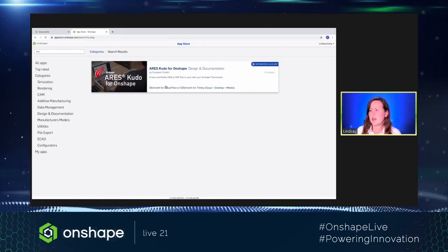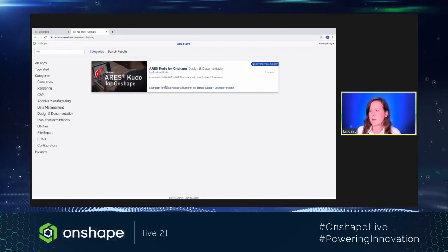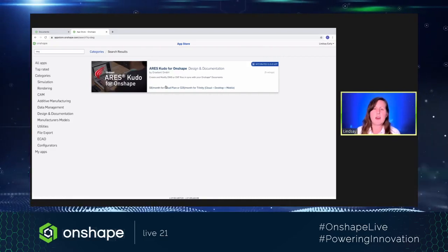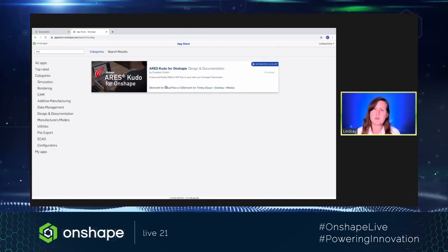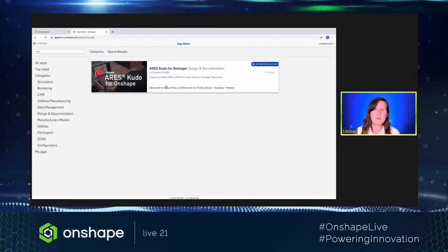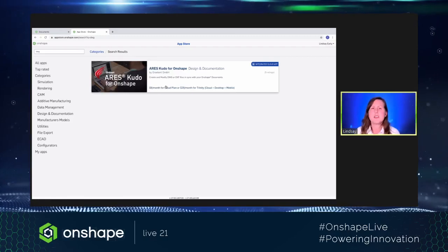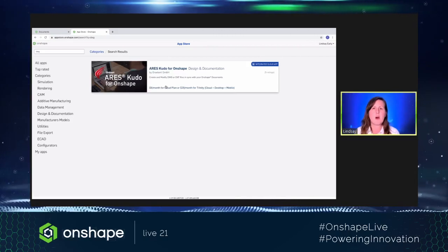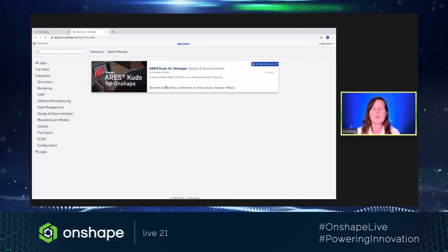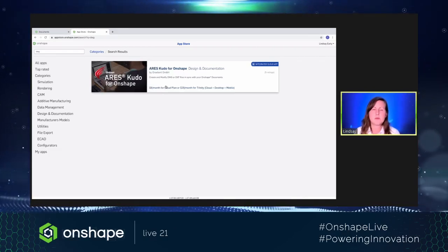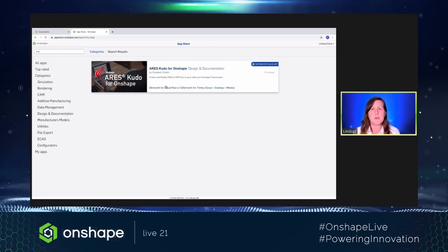So someone asked, do you have any best practices to get assemblies into working shape once we start our migration? So if there shouldn't be any movement in the assembly, the easiest way to get going is just go ahead and highlight the whole thing and use a group mate. The way that works is it basically locks all the parts with respect to each other. So when you put it in a higher level assembly, they're not going to move all around on you, because in Onshape, all assemblies are considered flexible. So if there's no movement, I would just do a group and call it a day. If there is some movement, then you'll have to get into using the mates.